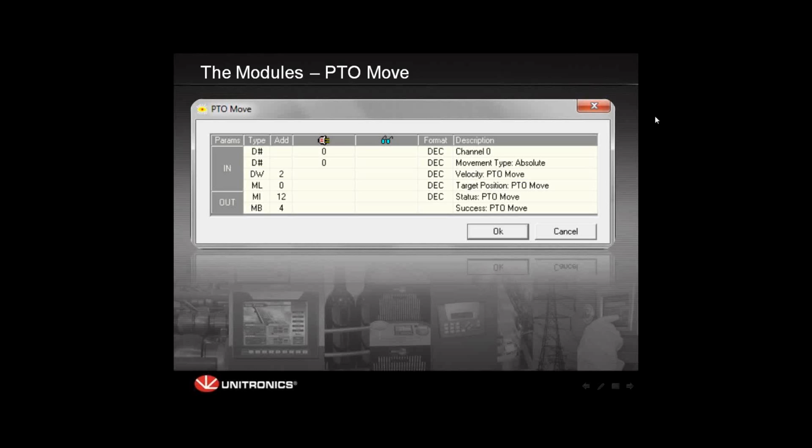The next thing we decide is the velocity. Now, this is not the maximum velocity that the movement profile can provide, but it has to be inside this range, because we cannot set a velocity for a movement that exceeds the maximum velocity we set in the profile.